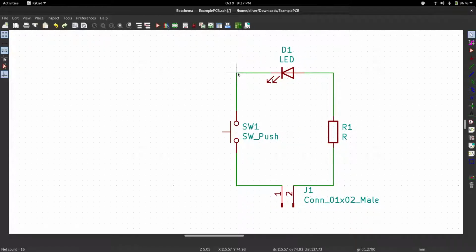It is very important that you set up good design rules that make sense for your project. If you're making a little low voltage PCB, like a hat for a Raspberry Pi, you can get away with this not being a huge issue. But if you're making something that's got high voltage, you need to have rules so that the program will stop you putting a 0-volt trace next to a 500-volt trace. You could have arcing. There's danger. Anyways, that's my spiel. Let's design the board.